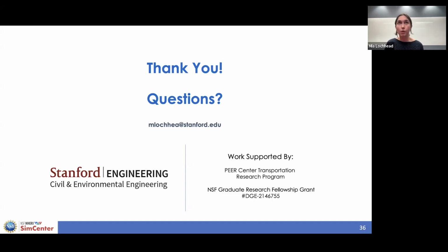Yeah, so that's a great question. The regional test bed that we're using is the Bay Area, but we've set this up to be reflective across California. Like I just mentioned, the ground motions we're hoping are somewhat comprehensive in terms of coverage of ground motions in California. And our bridge models were sampled to be reflective of the Caltrans bridge stock. There was work by a previous PhD student to look into different expected parameters in different Caltrans bridges. And so these are realistic bridges for how Caltrans is designing these in the state of California.